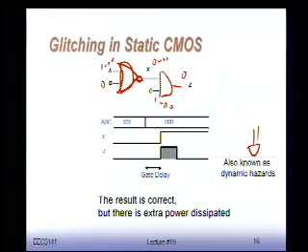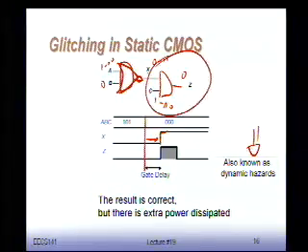But at the same time, at this particular time here, we change. With a certain delay, X is going to go to 1. Remember this delay. Okay? Now, what does this AND gate see here at that period of time? I'm not sure if it's an AND gate, but it doesn't really matter. It sees one of its inputs changing, but the other input, X, will change, but actually is changing a little bit later. So initially, it sees here, while I'm 0, this is now going to 1. This remains at 0. It goes to 1. I think it's another NOR gate.